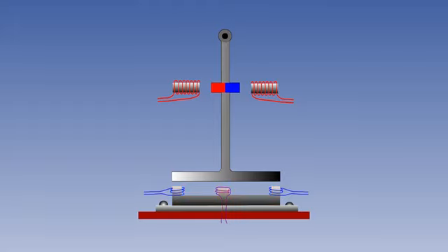A source of primary current is applied through a coil winding round the centre leg of the E-bar. If it were DC, this would convert the bar into an electromagnet, with a static north pole at one end and a south pole at the other. However, the primary exciter source is AC, usually at 400 Hz, and so the effect is that the magnet changes polarity every 400th of a second, that is, north to south and back to north again. Secondary windings on the outer two legs of the E-bar therefore experience a change of magnetic flux and pick up secondary AC voltages, the same principle as a transformer.